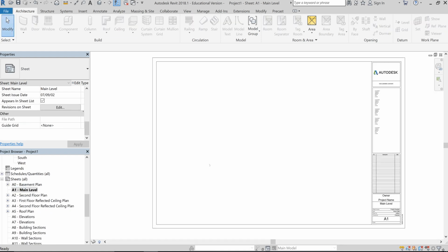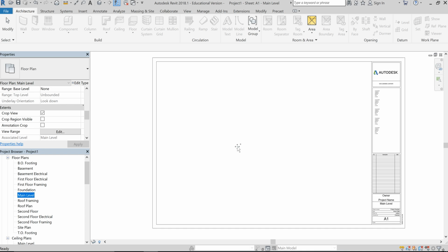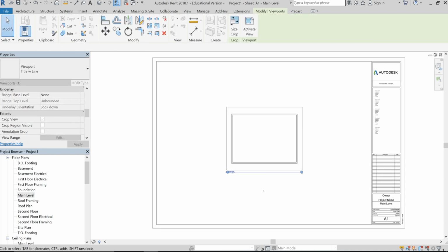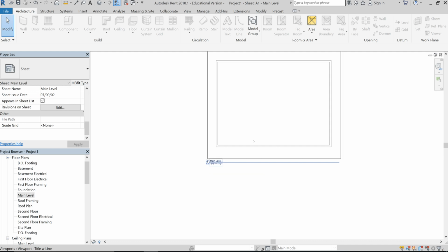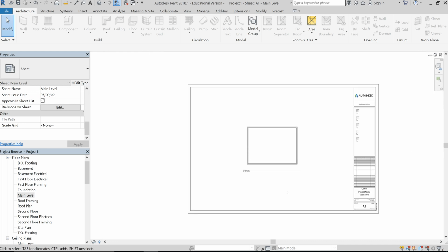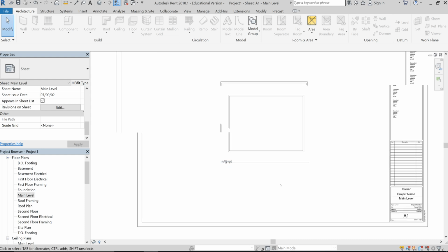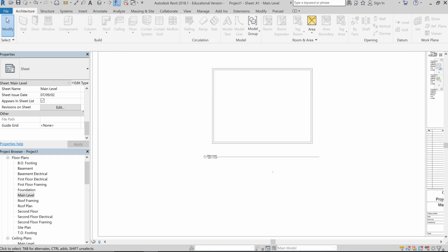Okay. So remember, at any point you can pause this lecture and go back a couple steps, a couple seconds. What I'm going to do now, the reason why I deleted it is now if I drag and drop it, see where that view title went? It's nice and pretty much perfectly aligned with my viewport. I don't like messing with the view titles. I'm going to show you why in just a second. If you want to move the actual title, I'll show you how to do it.